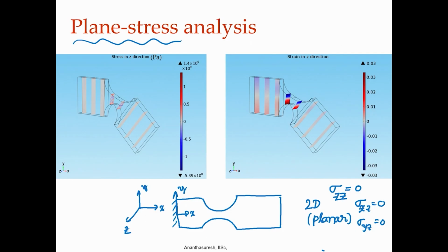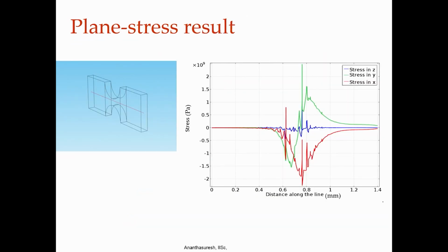How accurate that is, in order to find out, let us compare the stresses that exist in this device when we apply the force. Here the stress in the z direction is shown with the blue curve, and the stress in y and x directions are shown with green and red. So, now we see the blue one is much less compared to the green and red.